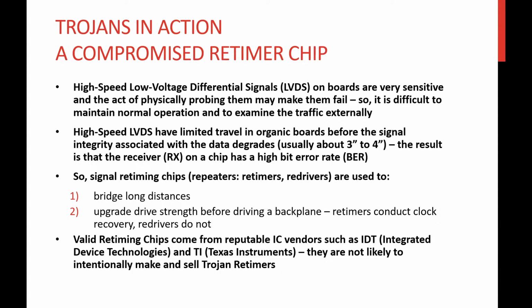A second method is to have a clock signal generated at the board or system level and to feed this clock to all devices. All chips synchronize data transfers to the same clock. And this is known as system or clock synchronized data transmission. These methods both have problems with distance versus clock skew.